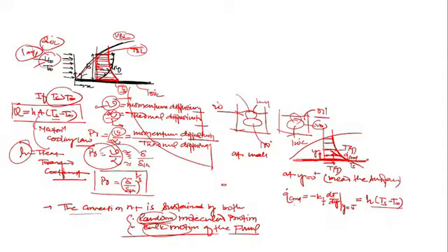It means the rate of convective heat transfer also depends upon the properties of the fluid. Yes or no? The rate of heat transfer depends not only on thermal conductivity but also on the density and the viscosity. These are called thermophysical properties. So, my dear students, you have seen that the rate of heat transfer is influenced not only by the flow velocity but also depends upon the properties of the fluid. Along with the velocity, it depends upon the thermophysical properties of the fluid.